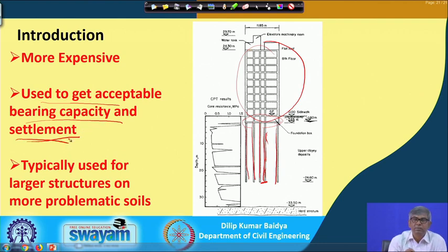Another reason why you go for deep foundation: sometimes if I adopt a shallow foundation for such a building, you may see that the settlement of this building may be significantly high, which is not permissible. In that case, by adopting deep foundation, we can restrict that settlement also, and it is typically used for larger structures on more problematic soil, which I have already mentioned.